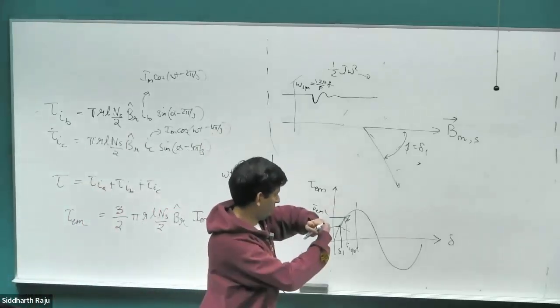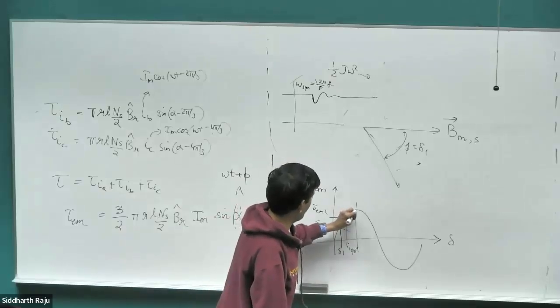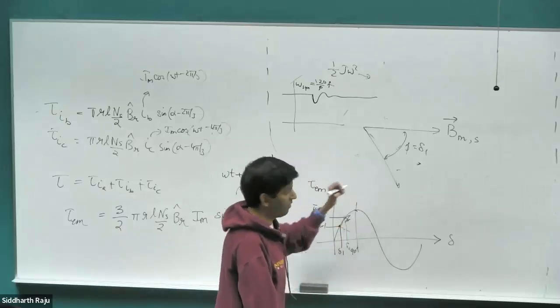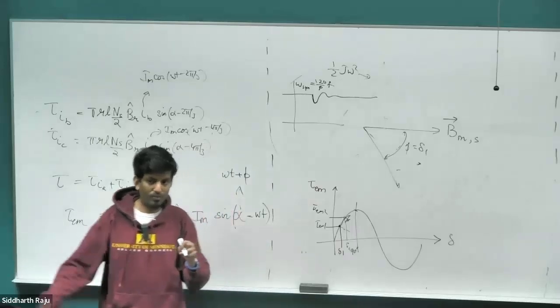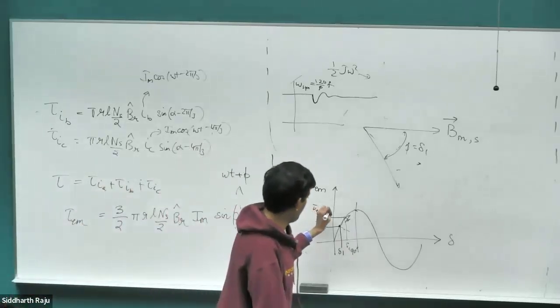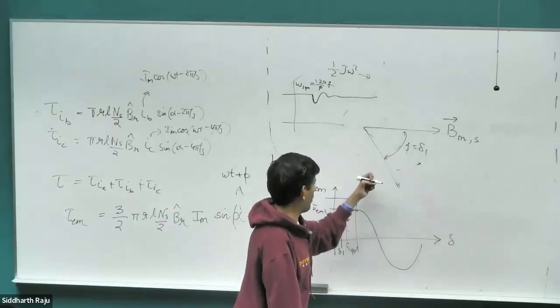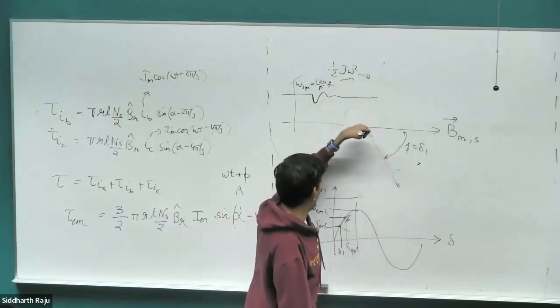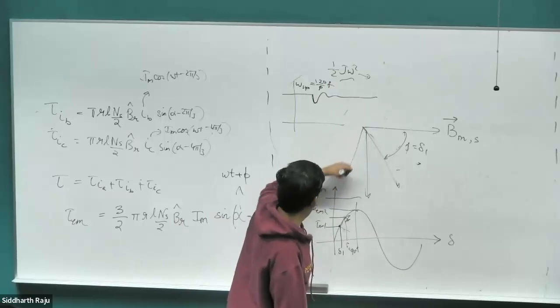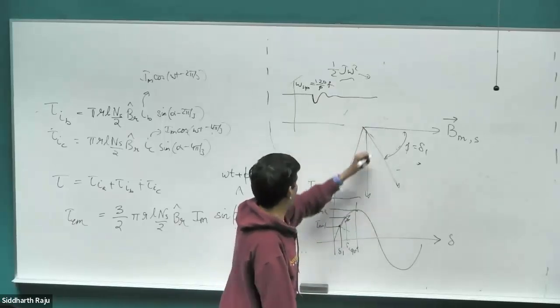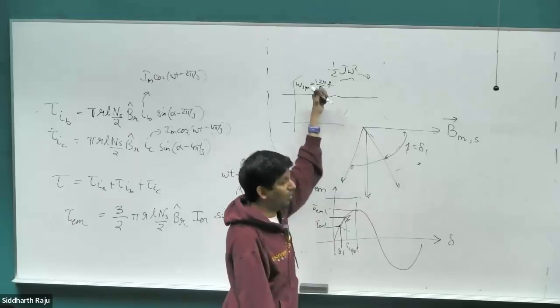Okay, so just 10 more seconds. What will happen if I reach the peak value and I increase my load demand just a little bit more? Go down. So if I go to the peak torque value and I still ask for more torque, then we know from our logic that the energy has to come from inertia. So the angle would go even backwards. So 90 is the maximum. After that, it will go even backwards because you're drawing energy from the inertia.